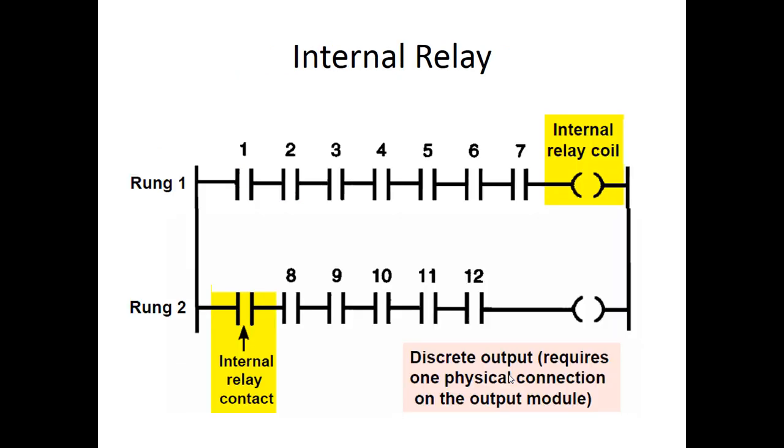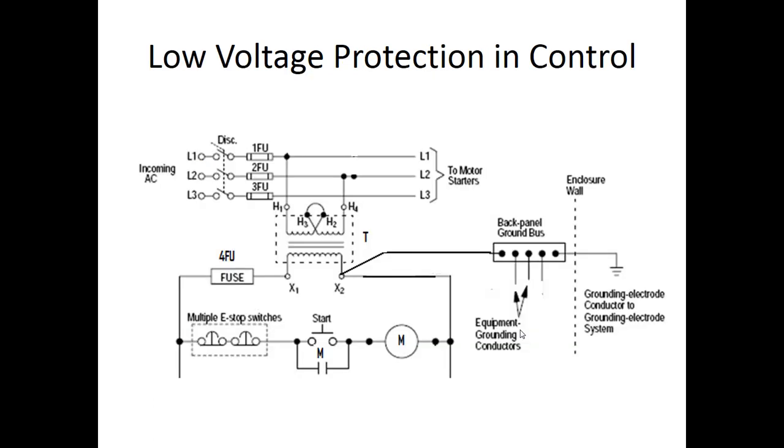So an internal relay, that's what I was showing there. If for some reason there's a limitation on the number of contacts that you can have, let's say there's a limitation of 7 here, and you need a 12, well, you can just turn on the bit and then put this next contact down here as that bit. So what you've got is a big AND, 1 and 2 and 3 and 4 and 7, 8, 9, 10, 11, and 12 turns this on. But if you couldn't fit them all in the same rung, you just wrap it right here. You just kind of create a little series where this turns on and that shuts the next contact. And then you've continued your big AND circuit.